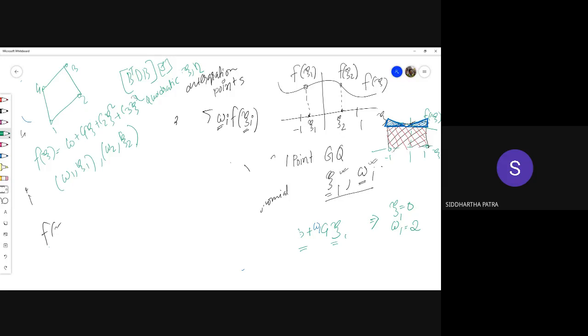Although for a four noded quad element which is a parallelogram in physical coordinates, to exactly evaluate the stiffness matrix we need to integrate only up to a quadratic term, we choose the weights and locations of the integration points such that it can exactly integrate up to a cubic function. Why so?